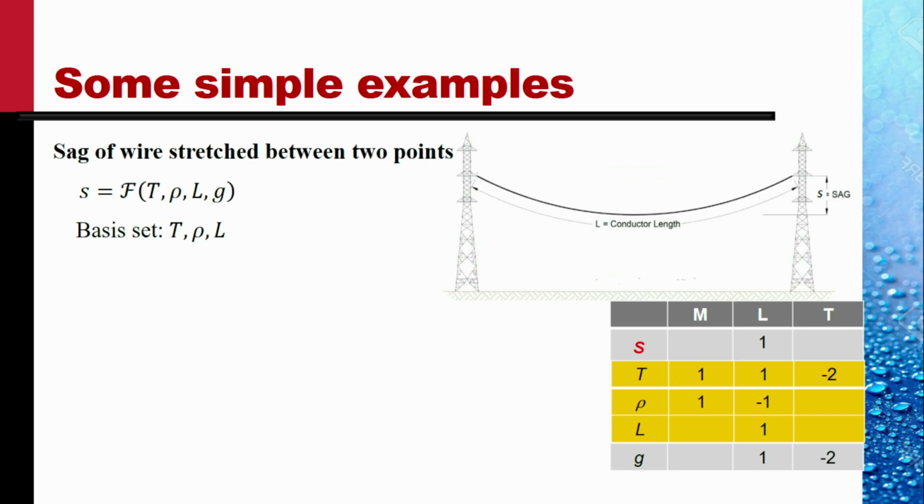We cannot form a non-dimensional group out of these three. Powers of these three multiplied together will not give you a non-dimensional group. So they are independent. They are complete because from these we can extract the dimensions of mass, length, and time.